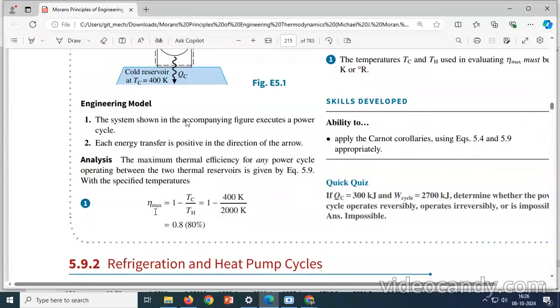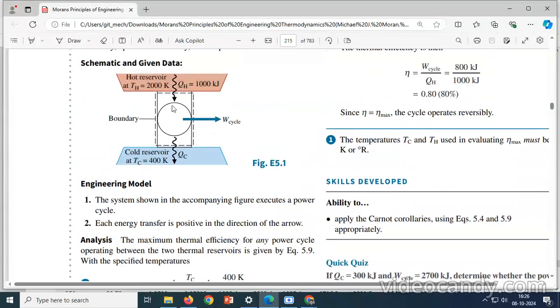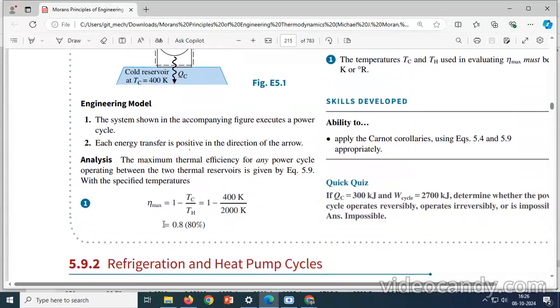So first case they have given the efficiency 60%. I'll write the efficiency of the heat engine by using the second law of thermodynamics or this diagram. Don't keep in mind that the efficiency of any cycle is the same thing. It depends on the given problem. Here in the problem they have given only temperatures. From the second law, I'm writing this equation for the heat engine.